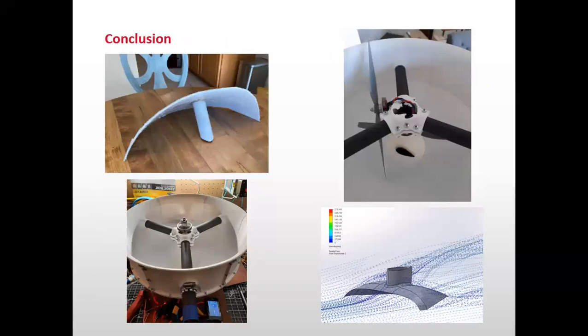The results from the wind tunnel testing of the 7th scale model showed that our CFD simulations were on the conservative side. This leads to the conclusion that the airfoil design is adequate in producing the desired lift for the projected combined weight of the rider and vehicle during forward flow regimes.